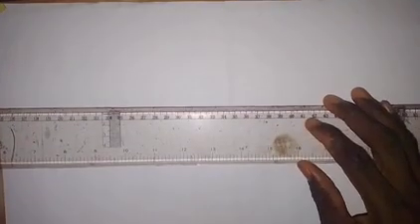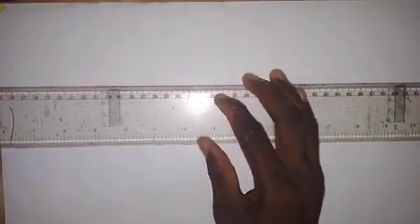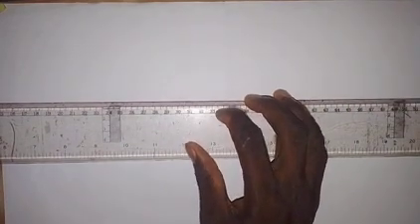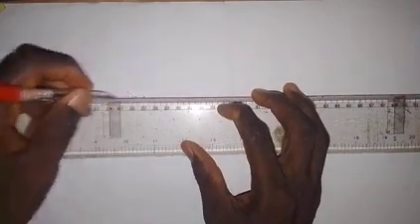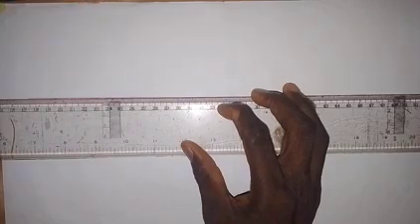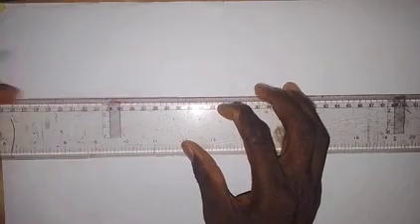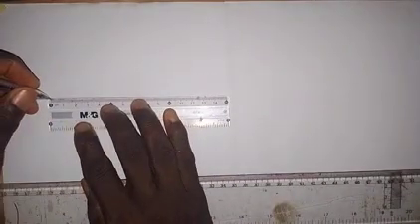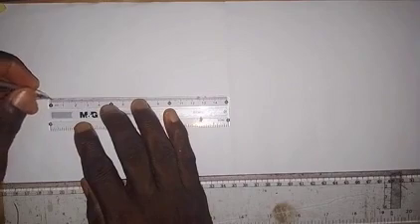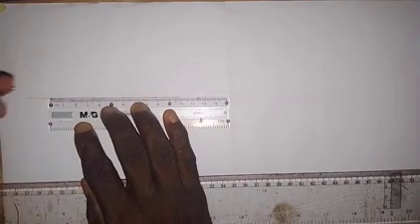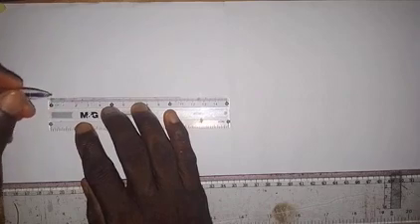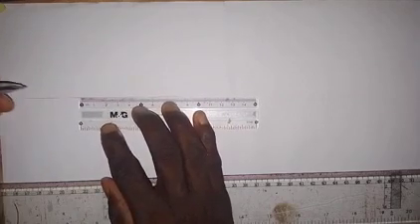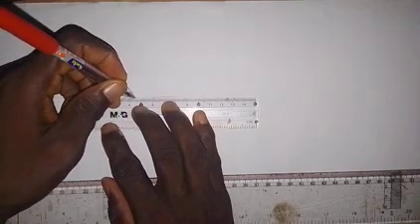Now the first thing that we need to do here is to draw a horizontal line. So just look at how I'm going to do it. We draw a horizontal line here as we see it in the diagram of the views that we are given. Then with our ruler, we are going to take a measurement. We take the horizontal distances first. So this is the first point on the horizontal line. Then we take 25 millimeters. Then after that we take 45 millimeters. Okay, this is 45 millimeters.